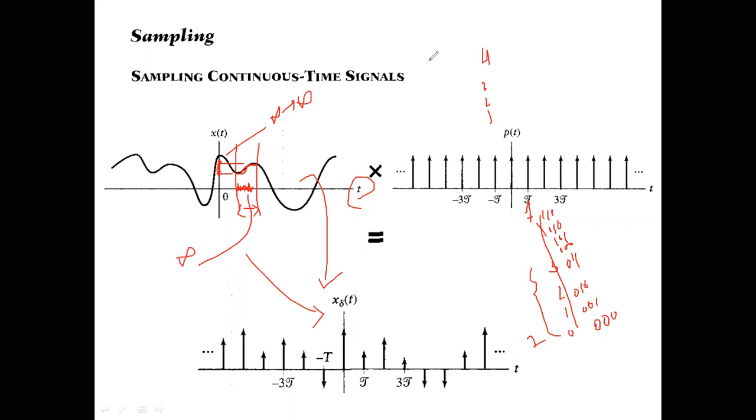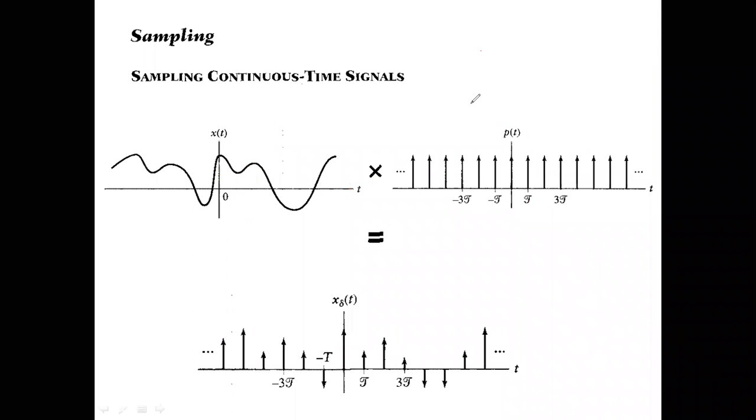What does a digital representation mean? Digital representation means something that contains only a finite number of amplitude levels, something like 1 volt, 2 volt, 3 volt, 4 volt, and so on. So amplitude levels are finite, and the samples occur only at finite intervals of time. In between the amplitude levels there is nothing. And you can see the amplitudes are also finite in nature.